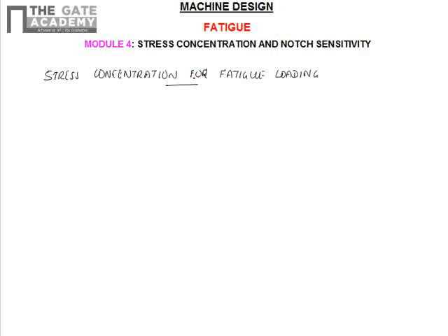But when we come to fatigue loading, before discussing about the stress concentration factor, there is another important term called notch sensitivity. We have to discuss this. The maximum stress in fatigue loading is given as Kf into sigma O, where Kf is called the fatigue stress concentration factor.